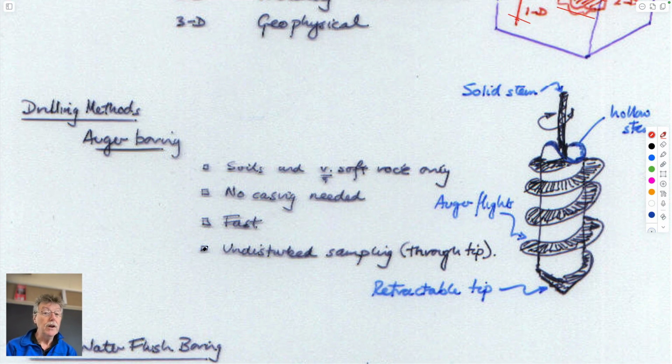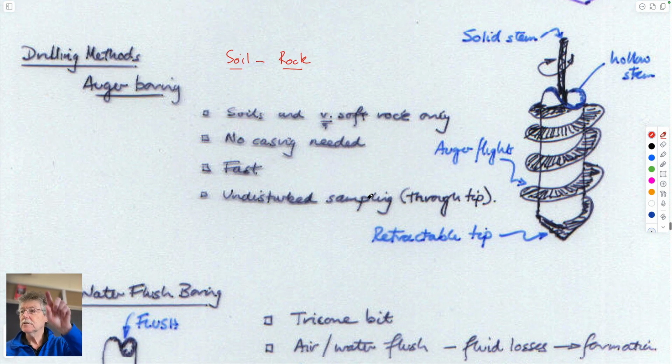But if we're doing drilling, then the big division is whether we're going through soil, which is obviously shallow, or rock. And the techniques that are used are different depending on that. Typically, to get to rock, you have to go through soil. And so you'd have to start off with a technique that allows you to get down to the bedrock and then continue on with a different technique, perhaps. And so the three main methods, which you might see if you're working as an entry-level engineer in these sites, the first job you'd go out to would be in soil, by augering.